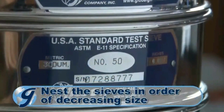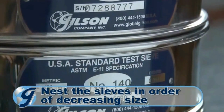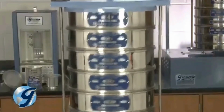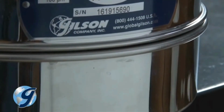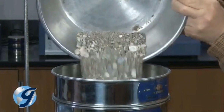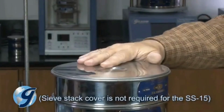Nest the sieves in order of decreasing size openings from top to bottom. Today, we're using Gilson 8-inch ASTM E11 stainless steel compliance grade test sieves. Place the sieve stack onto a sieve pan. Now place the test sample onto the top sieve and then cap the sieve stack with a sieve cover.